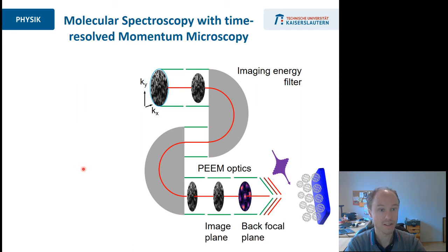For these fundamental studies, we don't consider large stacks of multilayers of different materials like metal-organic-metal trilayer systems, but we focus on model systems, which are typically a highly crystalline molecular thin film starting with one layer up to a few layers that are grown in a controlled fashion on metallic or semiconducting surfaces.